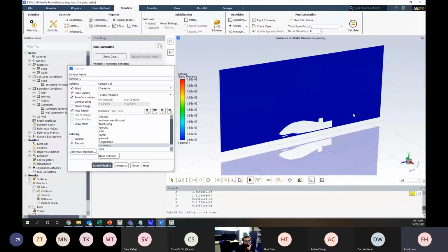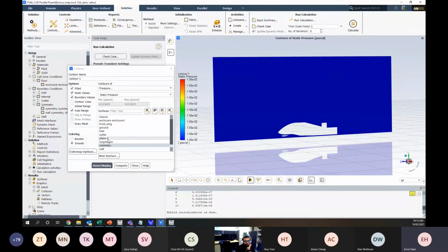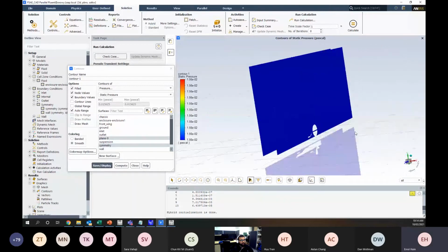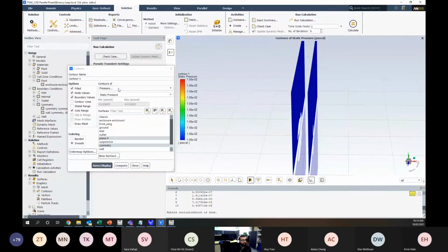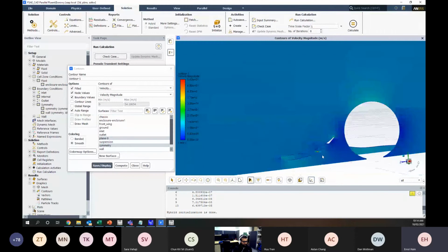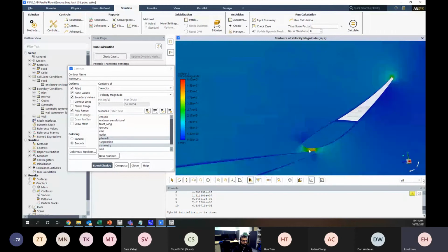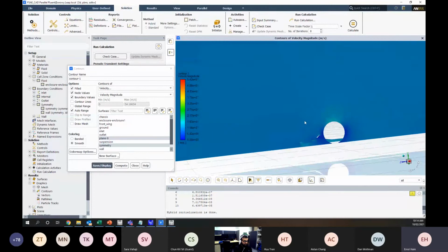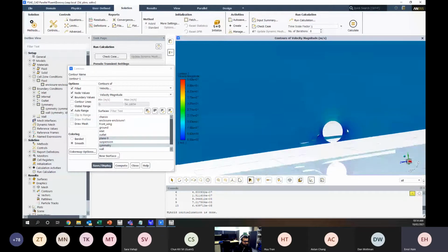So it's pretty constant pressure at the symmetry boundary. And same here. So that's our pressure. What's our velocity look like for these surfaces? We can see we've got some varying velocity. It's done a pretty good job. We know that that's going to be faster in there. But this is a really good way of understanding, okay, what's our first guess?